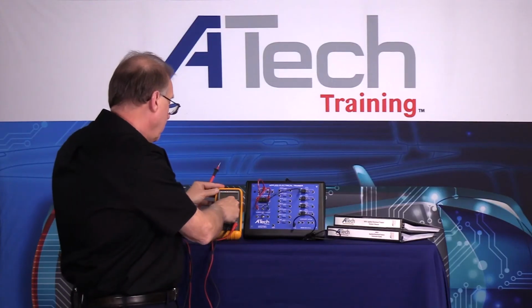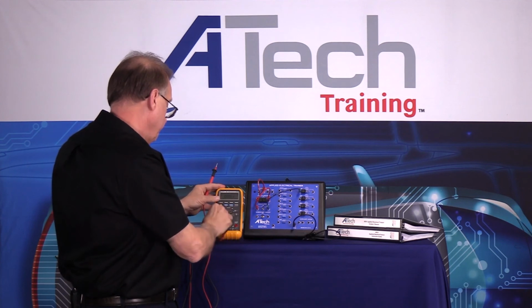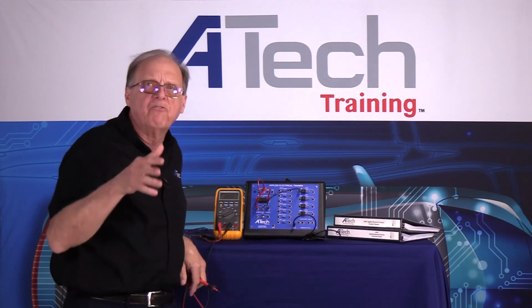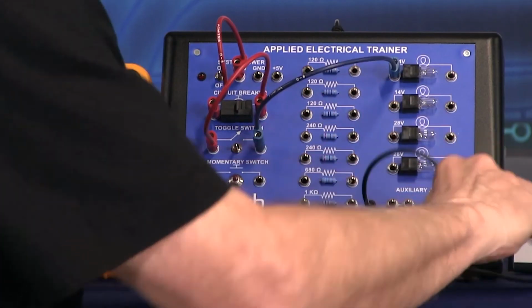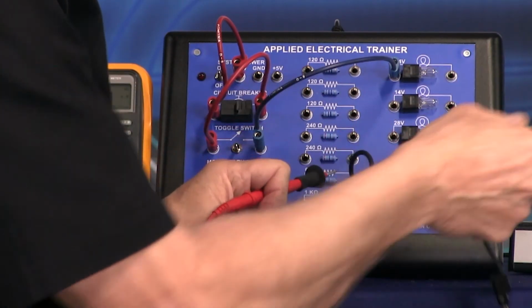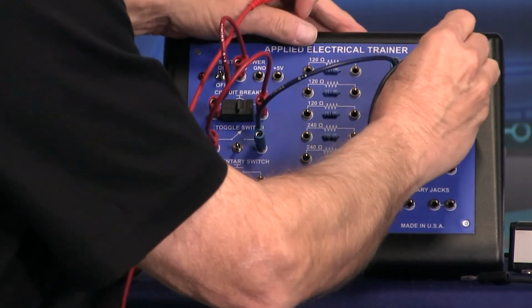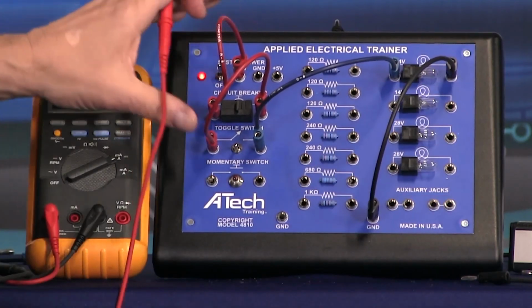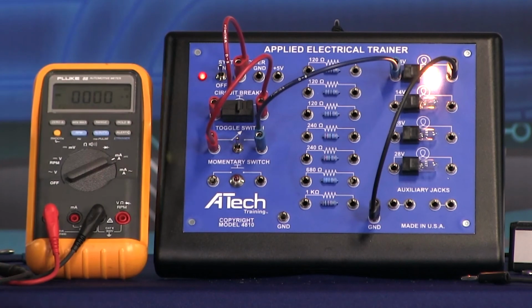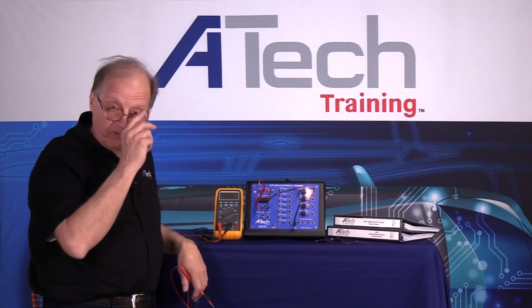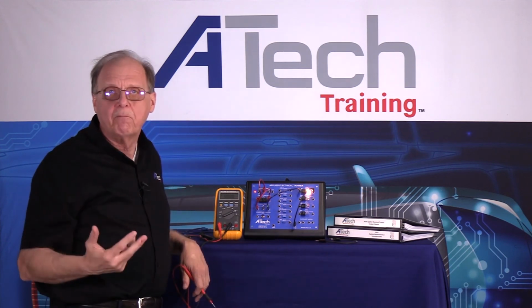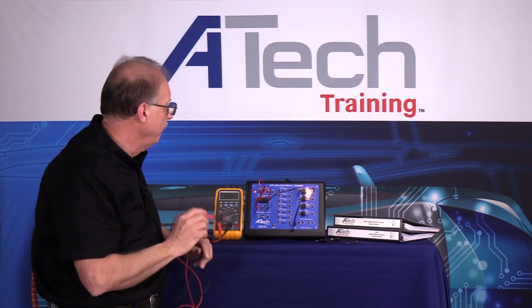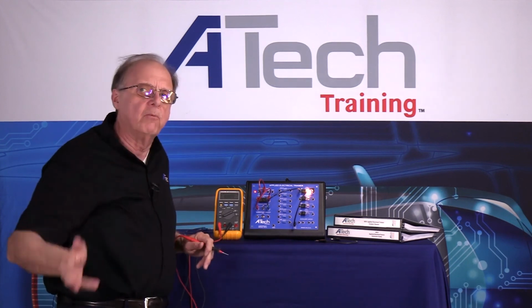If you're doing other things, when you use amperage, you must be in series. So if we're looking at this particular circuit, right now nothing's going on, I'll pull this lead off, turn the circuit on, and you notice the light is on. But to do amperage, you must break into the circuit. That's why a lot of techs and students have been learning to use low amp probes, because it makes it a little bit easier. But if I'm using the amperage on it, notice the voltage drops as it went across.